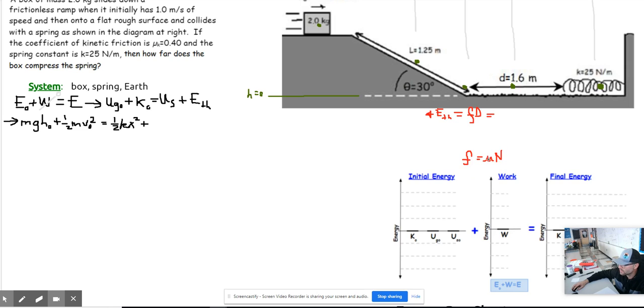How rough your surfaces are and the squeeze of those surfaces together produces your friction. So we can substitute those in here for our friction force. So mu times n is what that friction force is equal to. We still have our d. And we can also say, hey, normal force in this case is just equal to the weight, which is equal to mg.